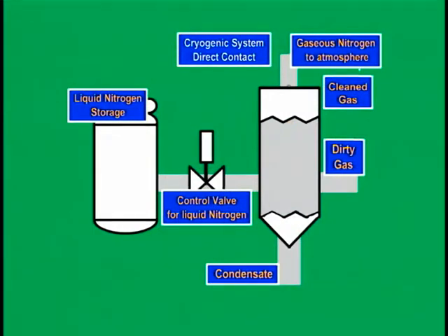Liquefied gases can also be used in direct contact systems. These systems also avoid the frosting problem, since there are no surfaces at extremely cold temperatures. The liquefied gas is injected through spray nozzles into an open chamber, where it directly contacts the contaminated gas stream. The chamber is insulated to keep the temperature as low as possible. Strip heaters may be mounted on the exterior of the chamber walls for the occasional removal of any accumulated frost from the interior surfaces.